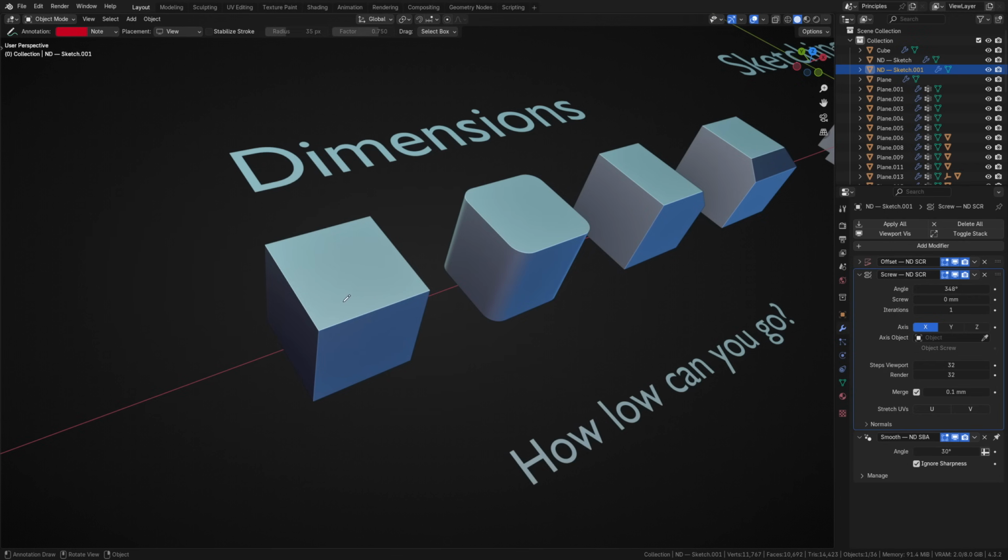A reliable approach to this is to use the idea of an imaginary plane, which is infinitely thin and can cut through anything. When used to slice through an object, this imaginary plane should result in a surface over which the object can be mirrored or extruded, and a cross-section which acts as a diagram or a sketch. We'll cover this idea of sketching in the next section.